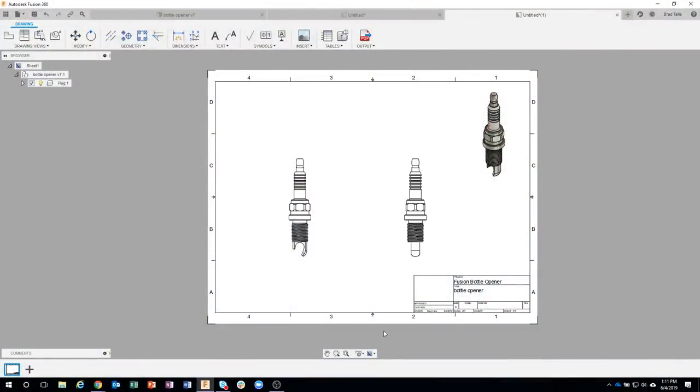And I will be honest, I actually didn't know I could do this until I watched Bryce's live stream he did a couple weeks ago about drawings, where he showed that you can actually change your sheet size after the fact. And I've always thought, man, I can't change my sheet size. Well, here's how you do it. Down here in the menu along the bottom, under Sheet Settings, if I click on this little down arrow here, you can see we have some options.